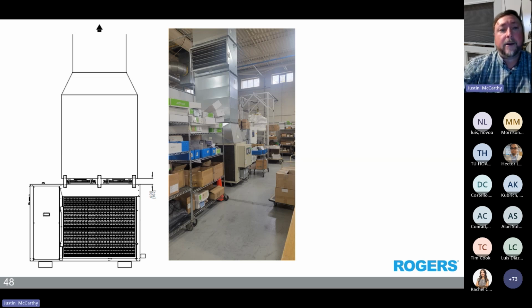What I'm looking at here, this wasn't my chiller, but the ductwork is attached to the unit. If you see my diagram, you should never attach the ductwork to the unit if it's a propeller fan. If it's a blower style centrifugal fan, you could attach. We call this a standoff, and we can't use propeller fans to pressurize a duct plenum.